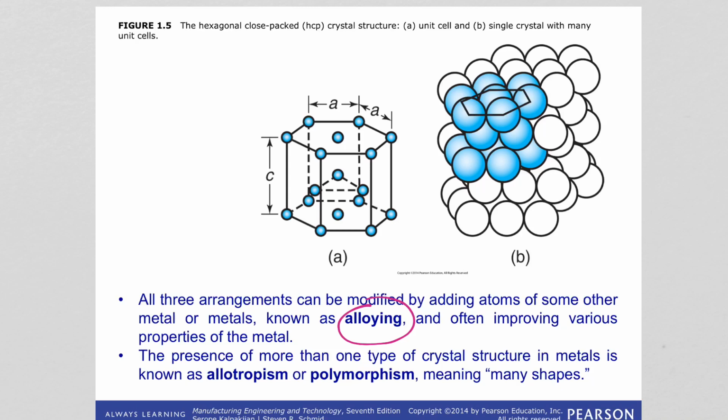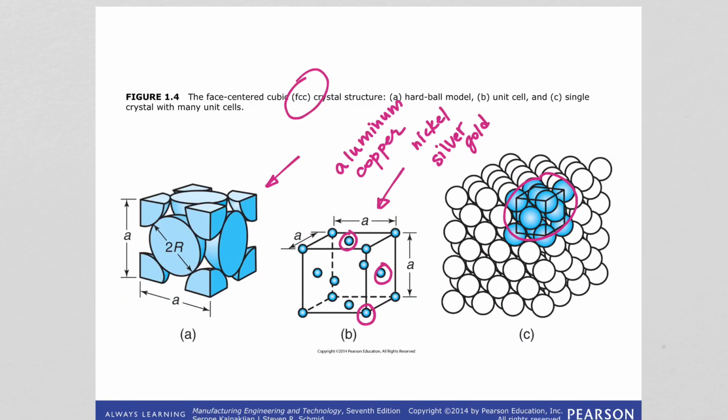Or when we say aluminum alloys, right? What do we mean? We have the aluminum, which is in FCC structure, and within those empty regions we are putting in different types of metals, but mainly it is aluminum, and the interstitial sites are incorporated with different metals and different elements, and this will give us what we call aluminum alloy, right?